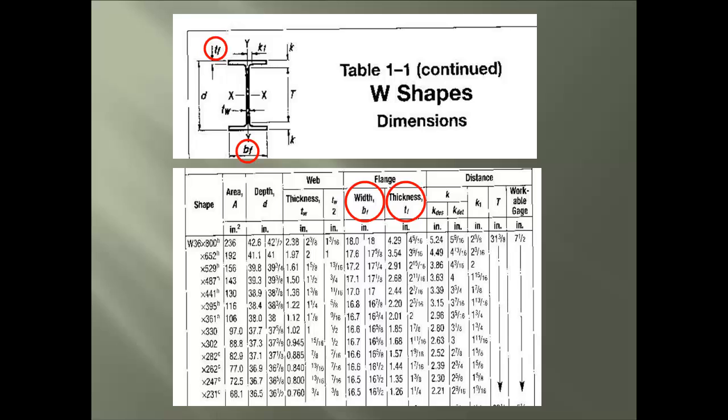A quick tip is, this column will alert you if UT testing is required. Because remember, the AWS D1.1 requires any plate 5/16 of an inch or thicker using a groove weld to be tested. And the last column is the information provided for the distance of the member.